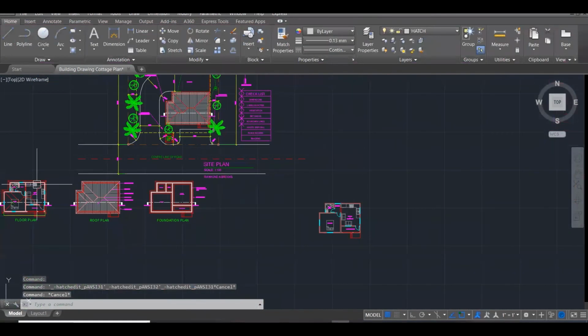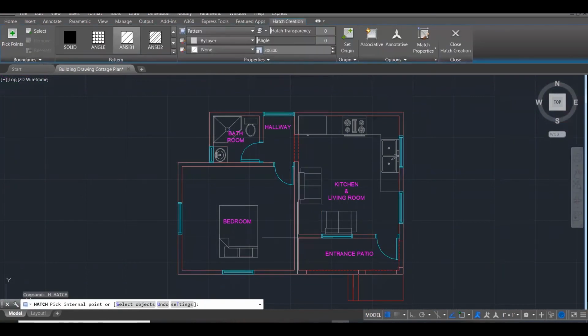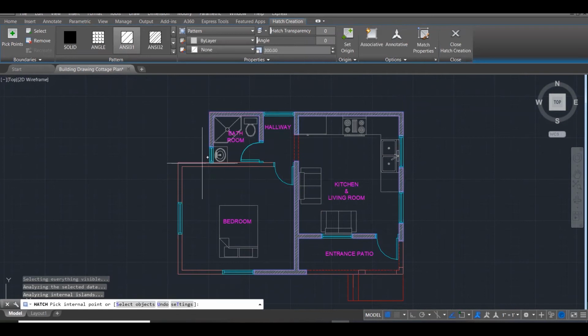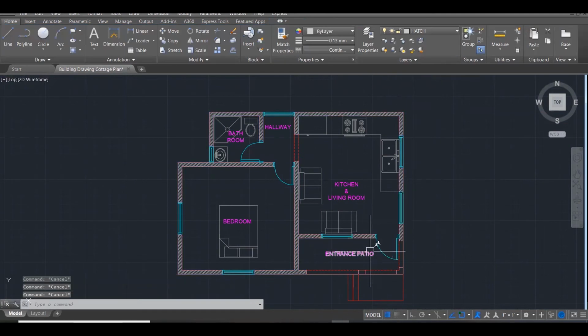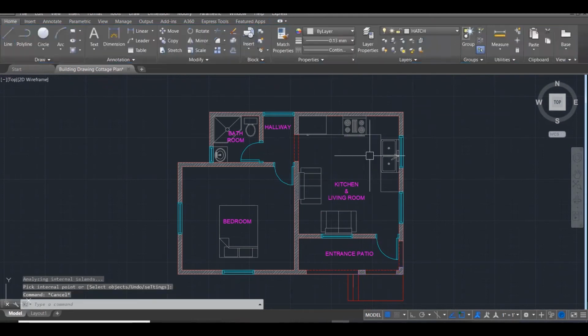Okay. So let me insert that. H to hatch, and I come here. That's in. I think seeing that was the last hatch I used on this file, it's default to that, so I didn't really have to check it out. It's all there for me. And with this hatch, now I'm going to put this as pure concrete in here for these columns. Or I can keep them as bricks. I know what, keep them as bricks. Keep it simple.